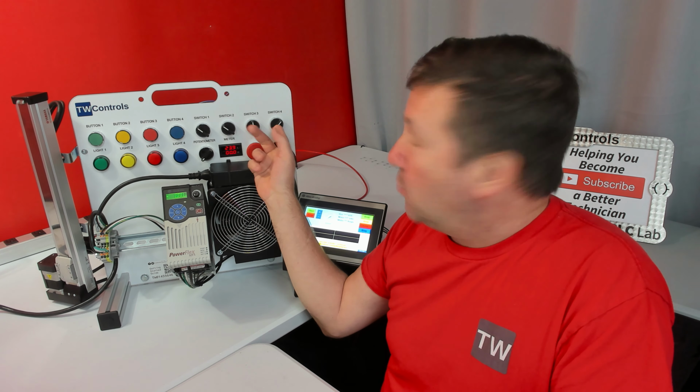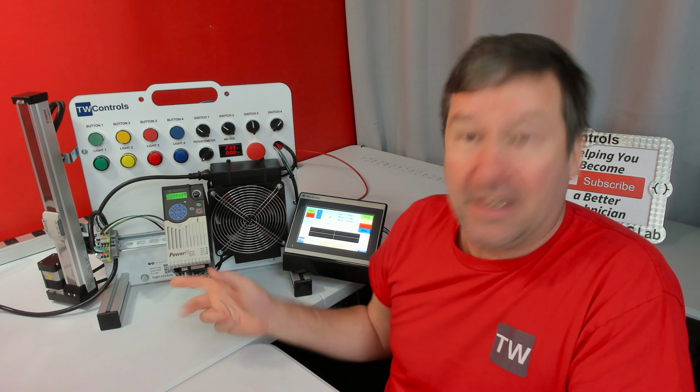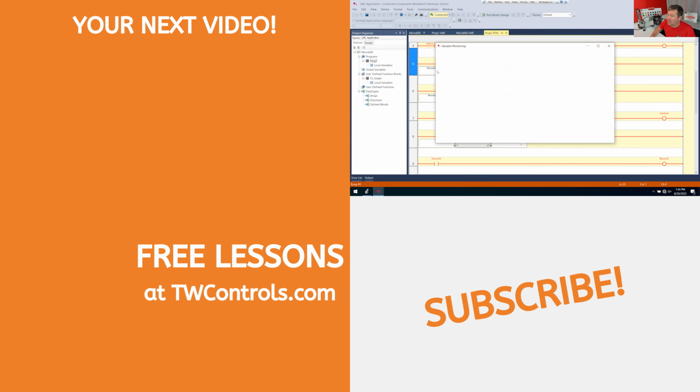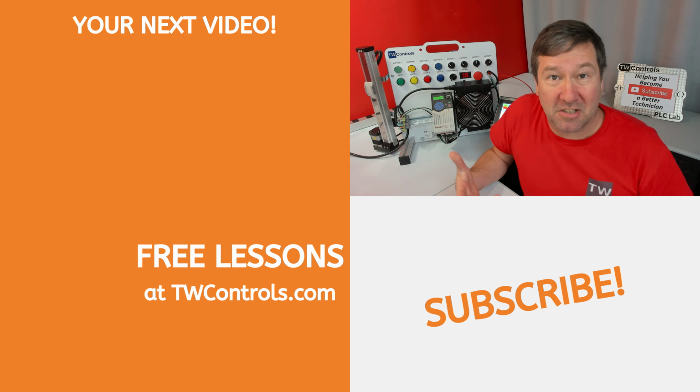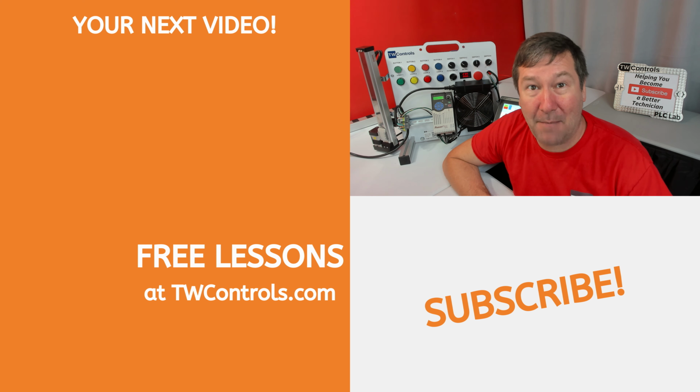Now, if we switch 4 to the center and then switch it back to the right, it moves up to 100 millimeter. And if we open up our move absolute position and we change it to 200, then when we press the enter key, it moves to 200 millimeter. Now we're ready to program a motion control application.